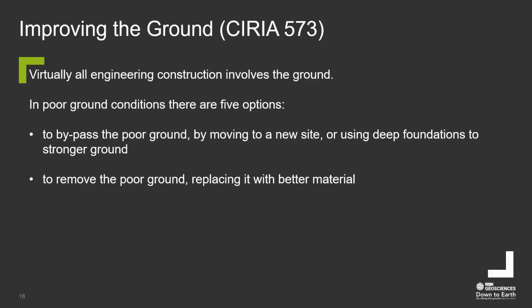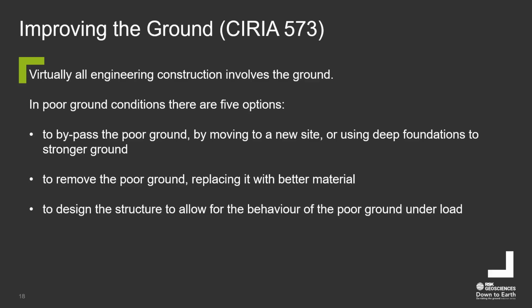Remove it and replace it with better material. Again, that was quite fashionable a long time ago, where we had available material that was easy to put in its place, but now, with transportation costs and what you're going to do with the material you're removing from site, it isn't really such a good idea. So we're probably going to want to keep it on site and try to improve it, and therefore the ground improvement techniques come to mind.